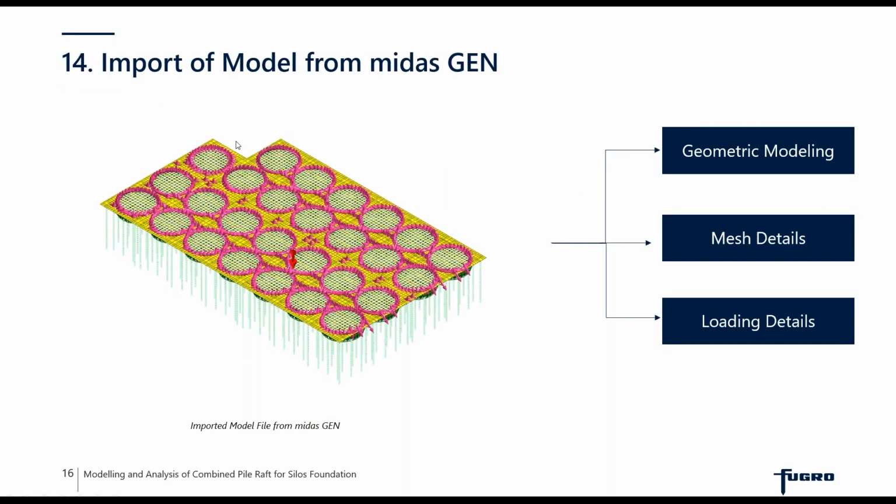The next important part is the import of the model from MIDAS Gen. If you are a MIDAS user, you will be aware that MIDAS Gen is the structural product used for analysis and design of buildings and general structures. In this particular project, the client provided a STAAD file. Now, MIDAS Gen has interoperability with STAAD and ETABS software, so any model which has been created in ETABS or STAAD can be imported in MIDAS Gen. And MIDAS GTS NX has a very good feature where you can import the complete structural model